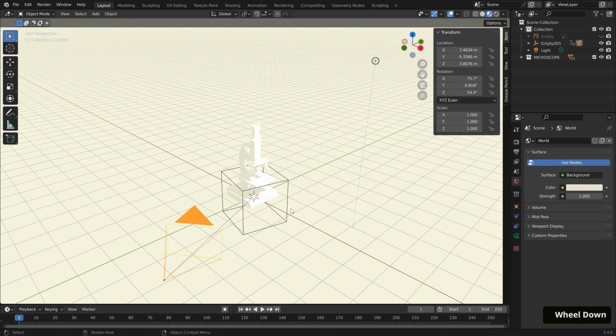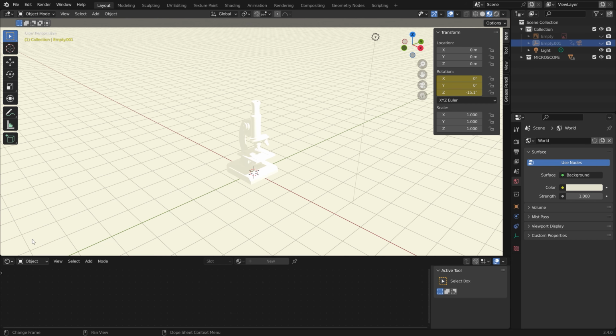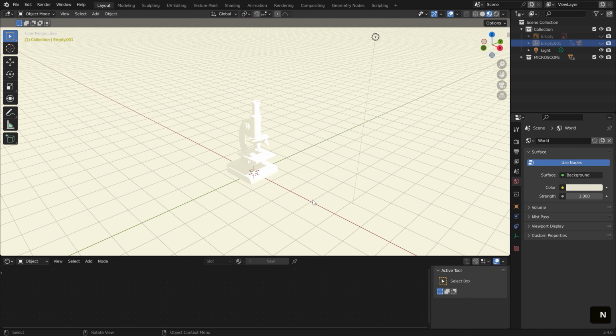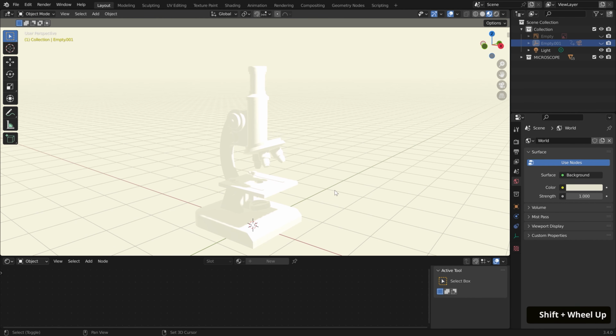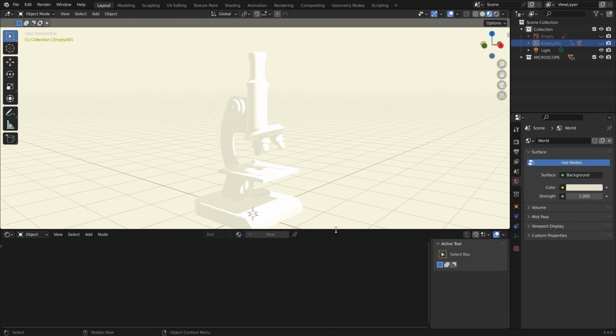Let's hide the camera object and cube empty by selecting them and hitting H. Then change the dope sheet down here to the shader editor and collapse this side menu with N. For shading, we have two main materials, a light and a dark color. They're pretty much the same except for the colors picked, and depending on which mesh they're applied to, a new material is created based off one of those in order to adjust specific settings. We'll start with the light material.